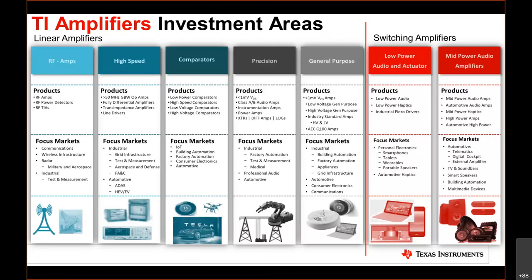These are devices with about 1 millivolt of offset voltage and above and less than 50 megahertz of gain bandwidth. These are devices designed for applications with cost-sensitive targets, any multi-sourcing requirements, and any projects with requirements for a small footprint or small PCB size. Our target markets are industrial, automotive, consumer, and commercial equipment. And if you have any interest in the other product categories, please stay updated with the new product updates that you can find at ti.com/NPU.